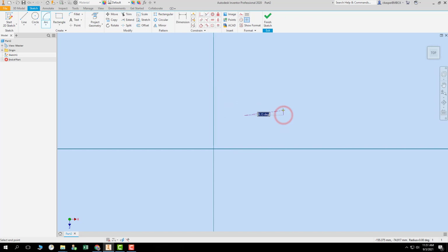I click again, and then I can start drawing my arc like that. There's my final. So this one lets you choose a starting point for the radius. You draw out your distance from the radius, and then you finally end with the curve. Kind of clever. So that's that one. Hit escape a couple times, get out of that, highlight the whole thing, get rid of it.